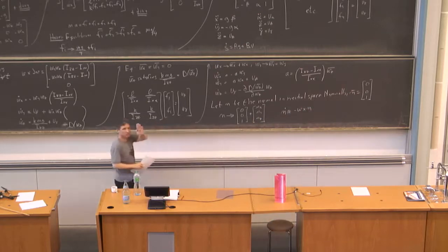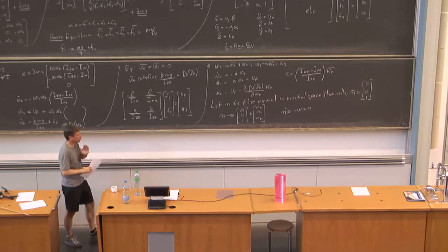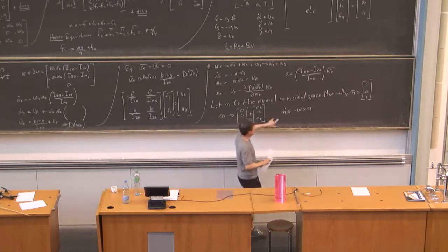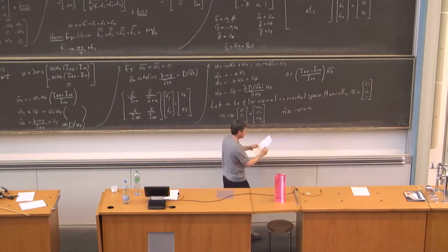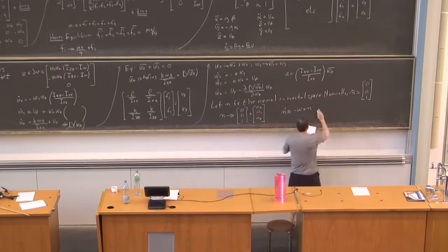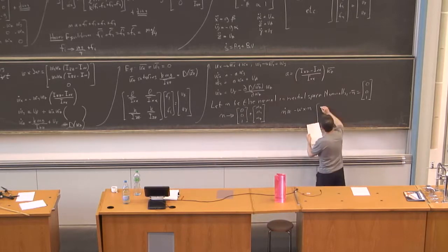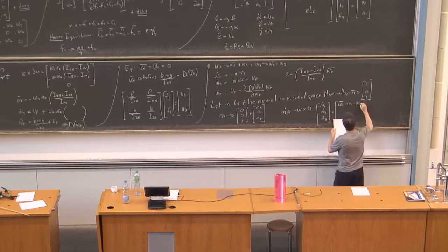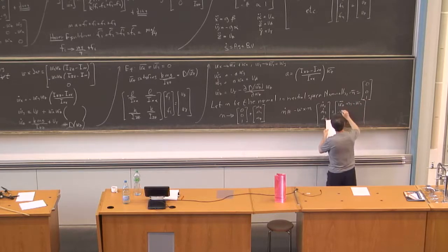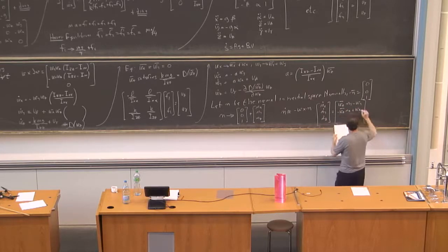Okay, so I'm assuming small perturbations around this normal that I want to point straight up, and the derivative of n is related to the cross product of omega with n. Okay, so if I form this, I get that nx dot, ny dot, nz dot is equal to omega sub z bar ny minus omega y, minus omega z bar nx plus omega sub x, and 0.